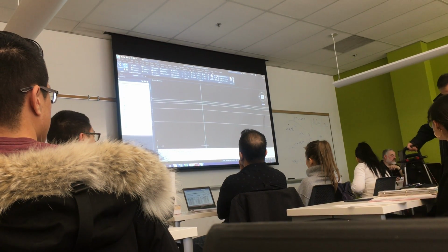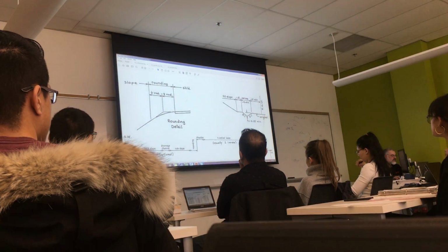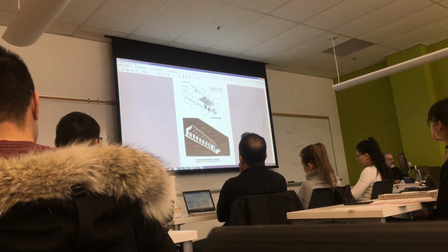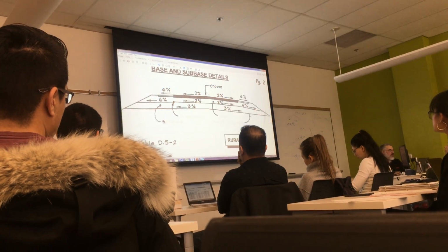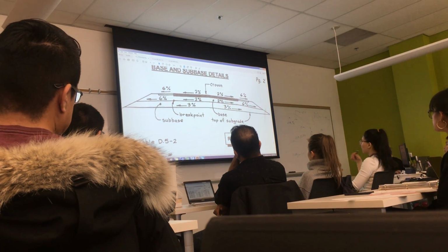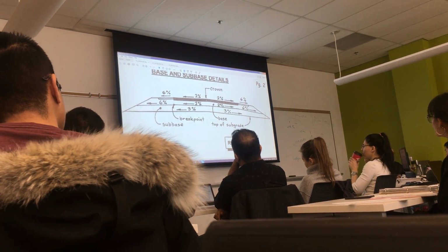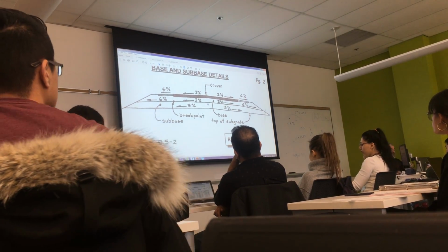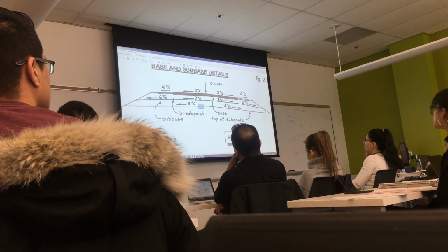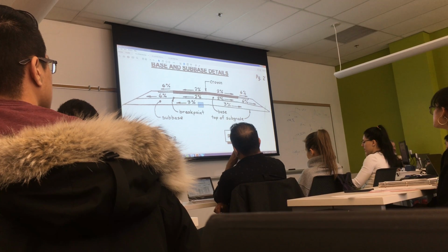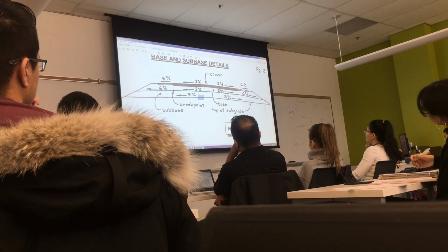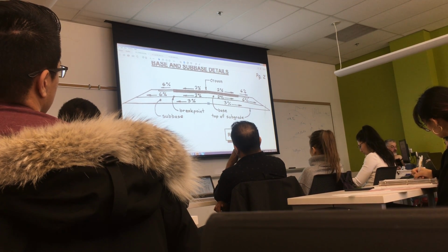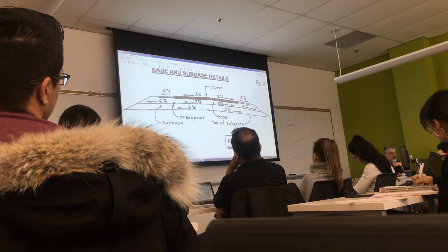Now, be careful. Don't forget to check this. I took my 2% and 6% plane, I copied it down for the first layer of asphalt, I copied it down for the next layer of asphalt, I copied it down for the interface between base and subbase, and then I copied it down to establish the subbase subgrade. Well, that's wrong. The 2 and 6% is true for all layers except the very bottom. The very bottom is at the bottom, it's going straight down in the center, right here. From here, go down 3% either side. So there's no more 2 and 6, it's just 3.